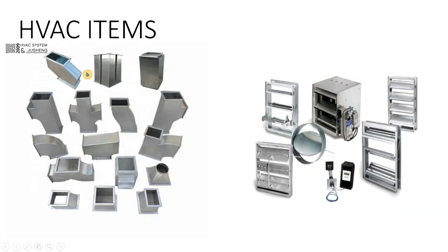The next one is duct fitting. These are all the duct fittings available when it comes to GI. It is applicable to all the ducts except for the flexible duct. For flexible duct, we will not use any fitting. We will simply join that with the main branch duct, and then connect it with the air distribution system, which is the louvers, air grills, or diffusers. We have different types of duct fittings available, as you can see in this picture, depending on your drawing and the area available on your construction site.